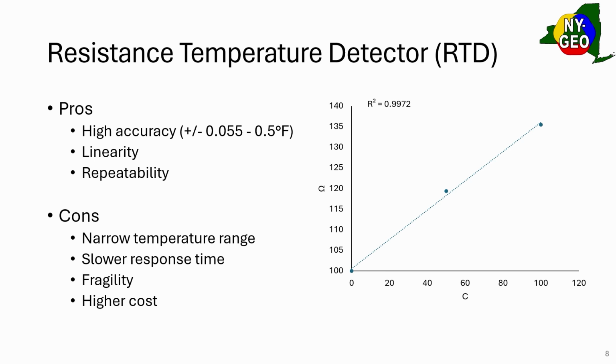Resistance temperature detectors, or RTDs, you've probably heard of these. Basically what this means when you hear PT100, it's made of platinum, and at 100 ohms, it's 0 degrees Celsius. So there's a direct linear correlation between resistance and temperature. And basically how that works is as you heat up a metal, the atoms get excited, they're bumping into each other.